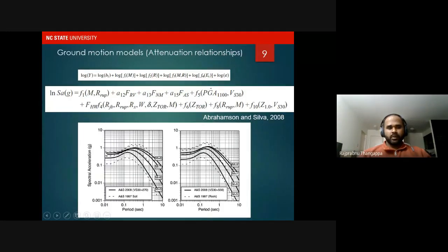As we already discussed how to calculate a response spectrum for a single earthquake record, we do those calculations for hundreds of earthquake records at a particular site, measured using accelerometers. Several organizations record these accelerograms, and they process them further to refine out the noise.